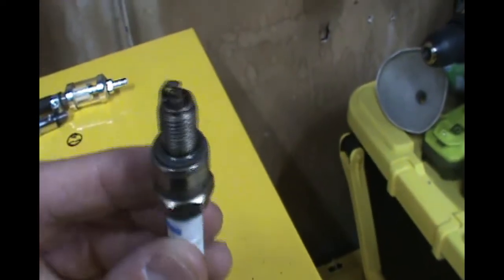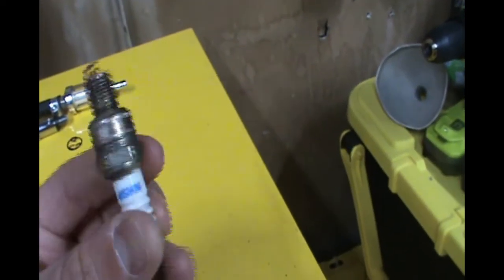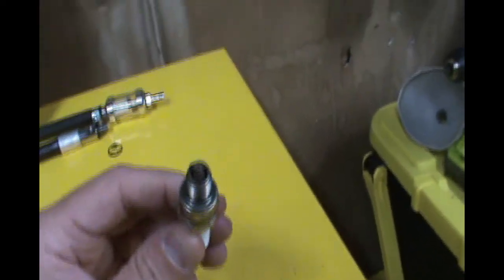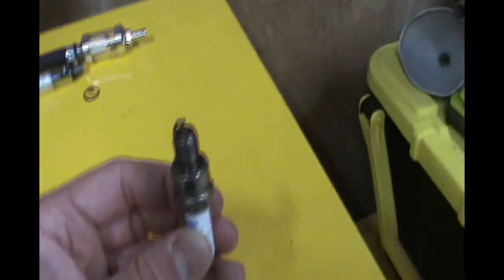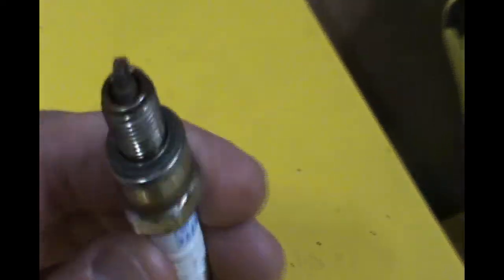But in order to determine if an engine is running properly, we just need to look at the color of the spark plug. So this spark plug came out of one of the dune buggies, and my focus isn't working all that well. There we go. You can see the color is a brownish blackish. In an ideal world with perfect combustion, this spark plug should be a tannish color, lighter than the tan on that wall, or maybe right around that tan. That's a nice water stain from the kayaks. But it should be a nice tan, and it should be even.